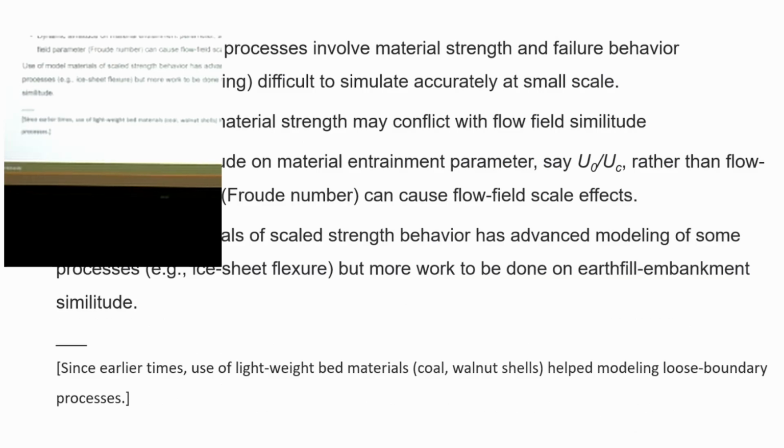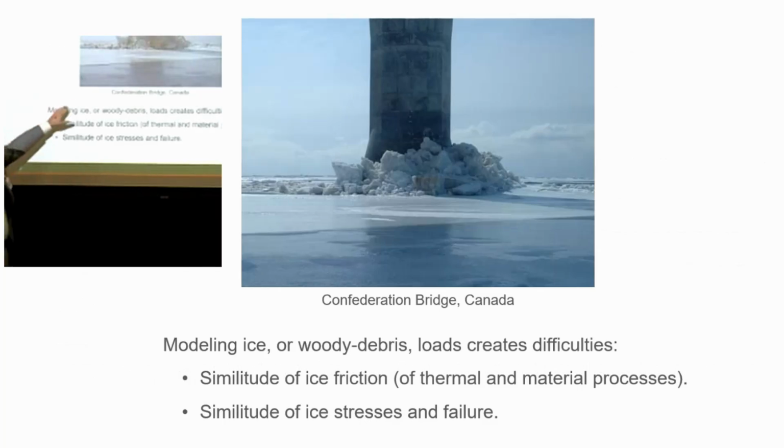Erosion of the soil materials very quickly. Modeling the strength of ice, for example, is very important. This comes up frequently, particularly if you're in Canada, designing bridges. You want the ice to fail in flexure, which, as I'll explain tomorrow, is one of the weakest strengths of the ice.